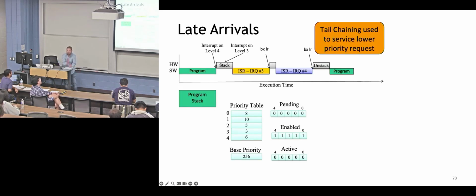Okay, do you have any more questions? Where do the preemptive and sub-priority numbers play into this? Would there be another base priority kind of thing? Yeah, so this is a toy example, but there would be 4 bits here allocated in some way, either all sub-priority or all priority or something in between. And if you had things of equal priority, they go into pending, and then the sub-priority decides the order of servicing things that are pending.